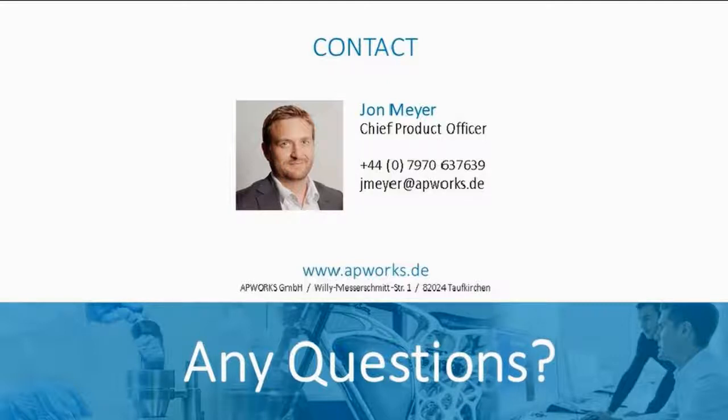So the question on whether it's an issue, I think I mentioned it earlier, but it is, yes. So obviously the surface finish is the most critical factor to fatigue crack initiation. So it's very important that if you have a fatigue-driven part, that you address that. That's not to say the fatigue performance is unusable in that condition. It's just a question of what stress you can tolerate for infinite life, and it's quite a bit lower with that surface finish than you can tolerate with a perfect milled surface finish.